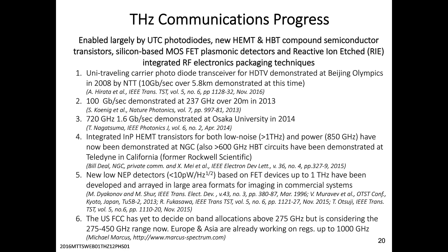So I guess the real draw here is that if you need bandwidth and you go above 100 gigahertz, there's plenty to be had, and you can really do some nice high data rate types of comm if you need to do that over reasonable distances. And there are basically 3 or 4 atmospheric windows you can work at, and I'll show you those in a... Wow, I am really running out of time, aren't I?